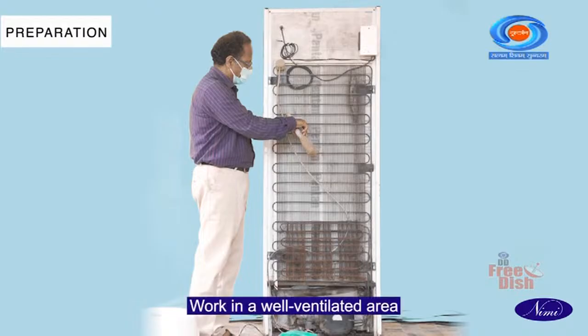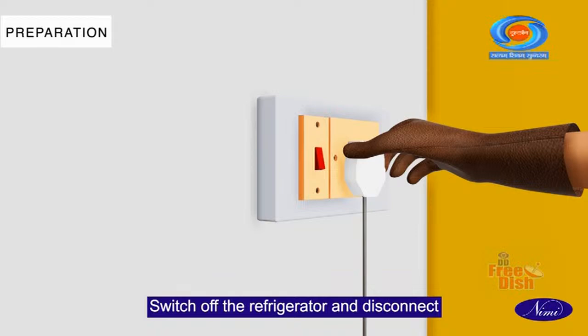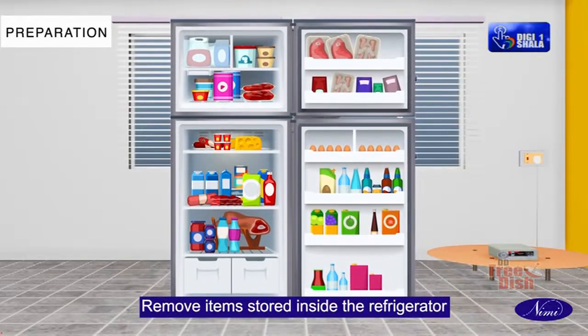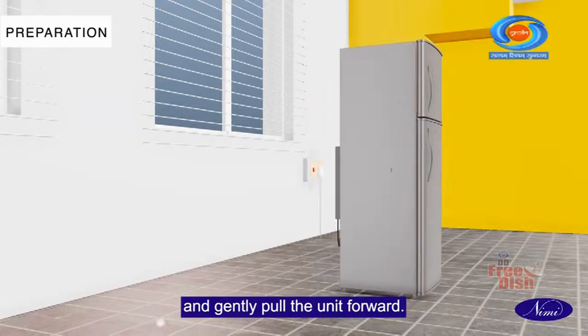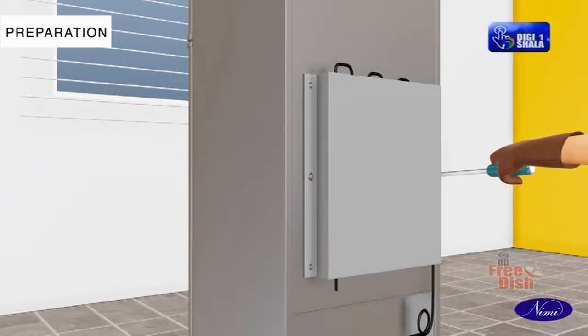Work in a well-ventilated area to avoid inhaling fumes or gases. Switch off the refrigerator and disconnect the plug from the socket. Remove items stored inside the refrigerator and gently pull the unit forward. Unscrew the back cover to expose the condensing unit.